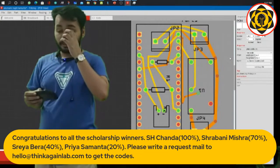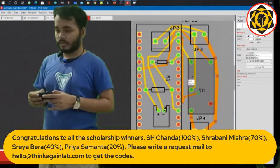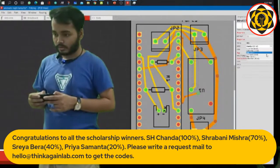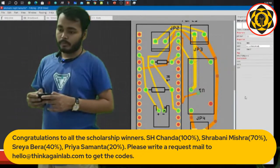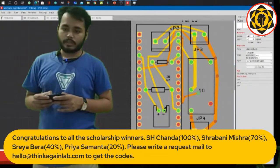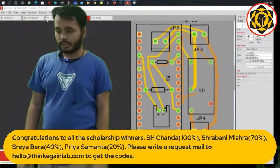Okay, that is done basically. We got all the power hungry connections into the thick wire. So that probably won't cause any problem anymore. So yeah, that's done. So now let's do our DRC check. Design rule check.